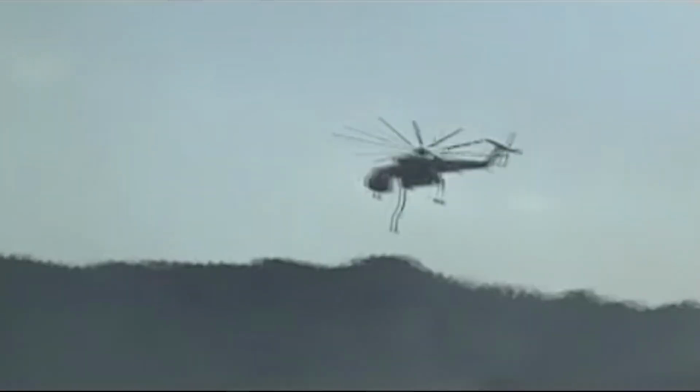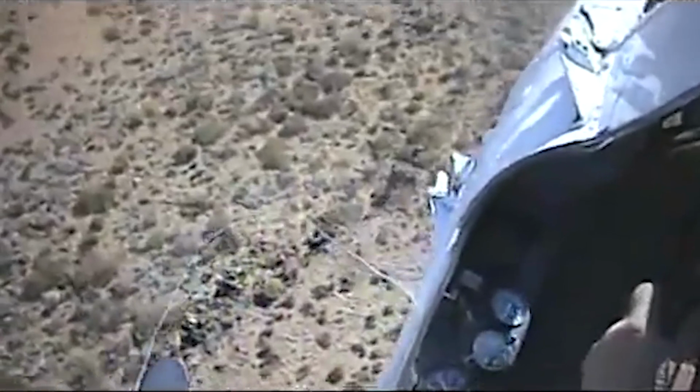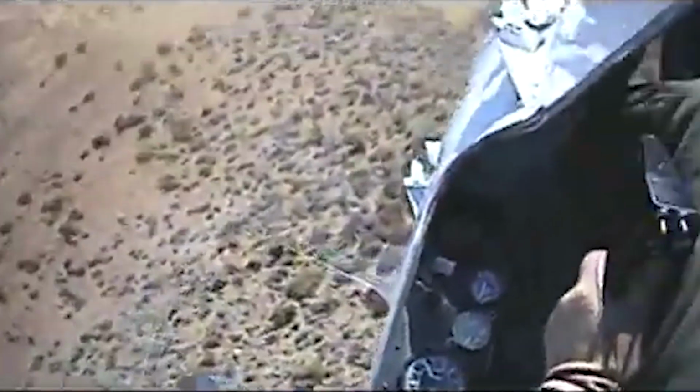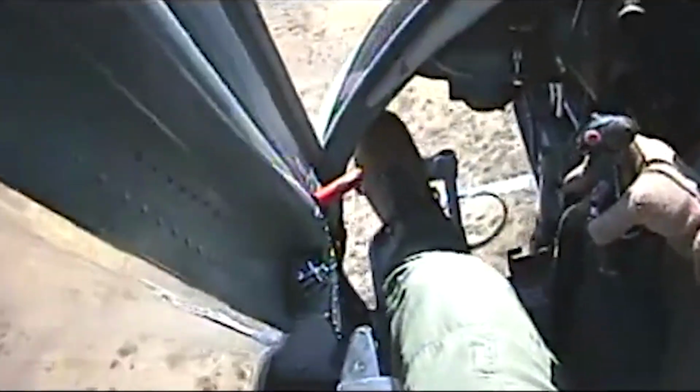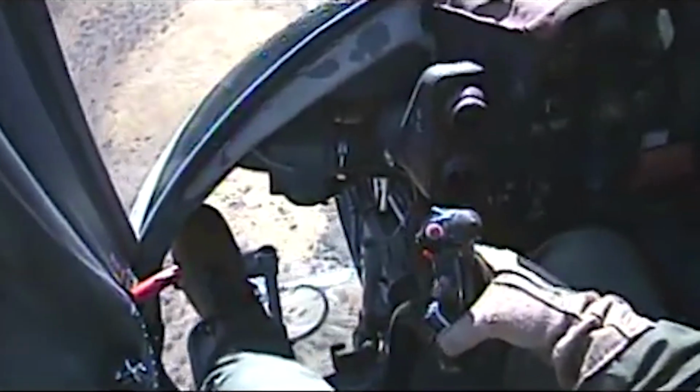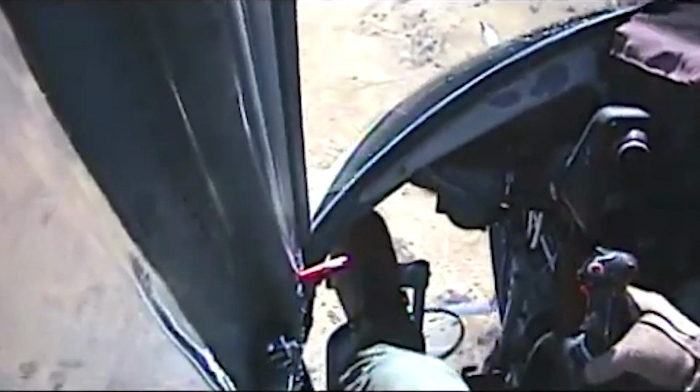A Type 1 helicopter can drop up to 700 gallons or more than 5,800 pounds of water. To be hit by the water itself may be catastrophic. When you tell the pilot the drop zone is clear, they may expect you to be farther away than you are. At points, they will not be able to see you. Get back farther than you think you need to.